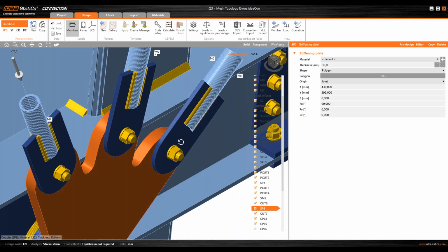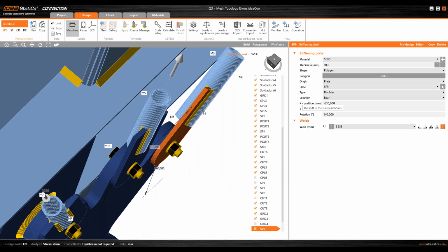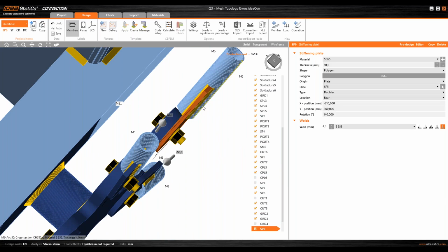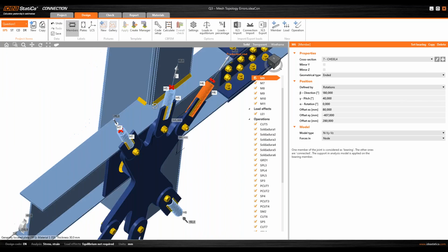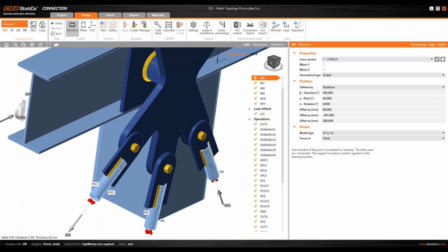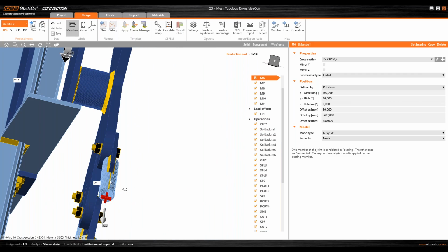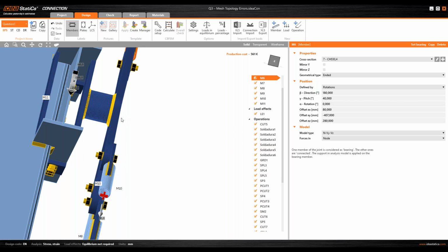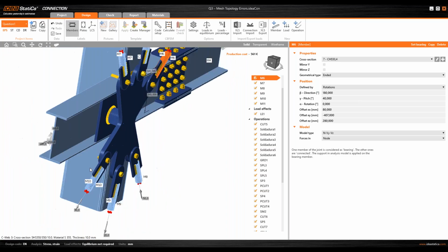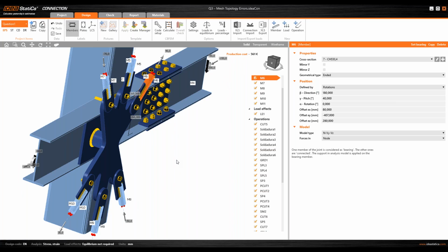If we take a look at this method, in this case with a DXF, we see that we need to move proportionally, we need to apply an offset for this connection bracing, in order to center it with the plate. However, the CPL, the connecting plate operation, automatically moves this bracing to adjust in the middle of the plate. So in this particular case, maybe it's easier to use the CPL instead of a manual plate with DXF importation.